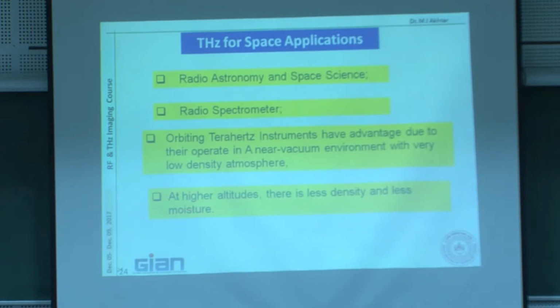For example, up there you have less moisture, that's perfect. Once you come to the ground, moisture is quite high, and you have quite high terahertz attenuation. Then everything, whatever you think of, high bandwidth and very fine resolution, all goes down. Even for communication purposes, people thought we can make a terahertz link and everything will be very high quality. But the problem is that it can only go just beyond 100 meters. So even for 5G millimeter wave, people are thinking about what to do because of putting in many repeaters, as the Professor was mentioning. So terahertz is something one step ahead.